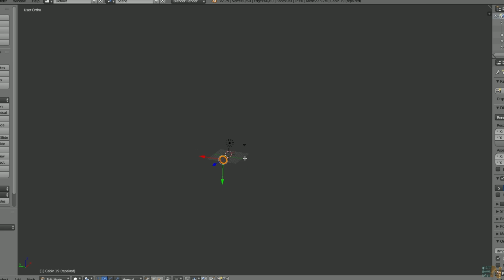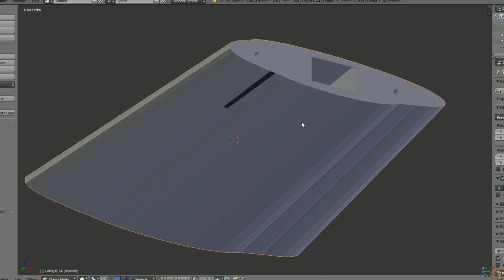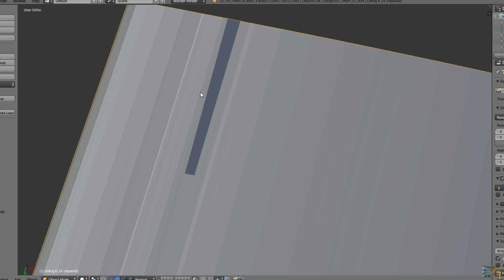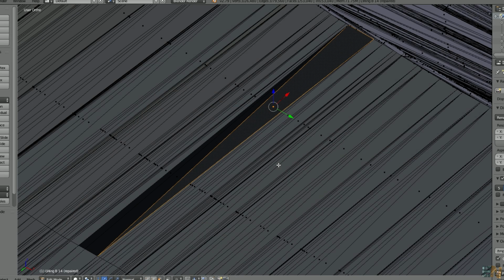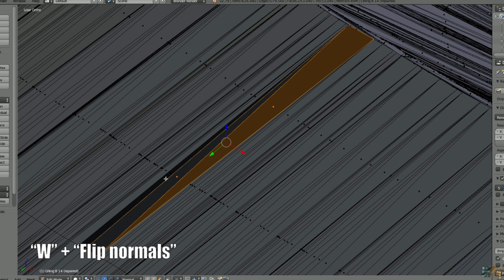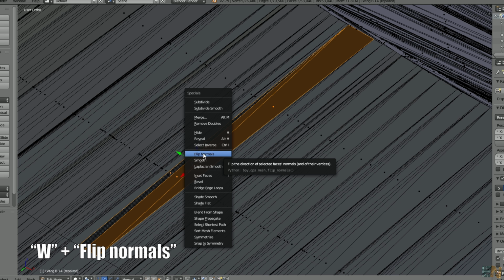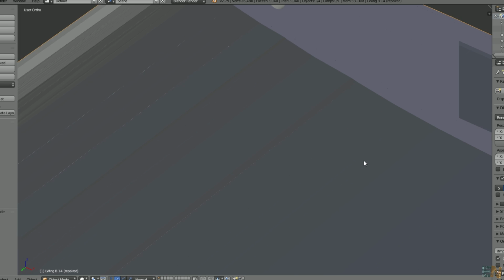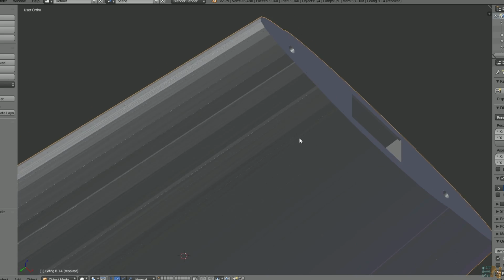Now for example you can press delete, and by that you will be left only with the points that you wanted. Also, while designing, you will see that one face of the object is darker and the other one is lighter. That is to represent which is the exterior and the interior. So if you want to flip any face, select that and press the double V key again. And now you have to select invert normal. And as you can see, now the face is flipped. You will definitely use this option a lot while designing.